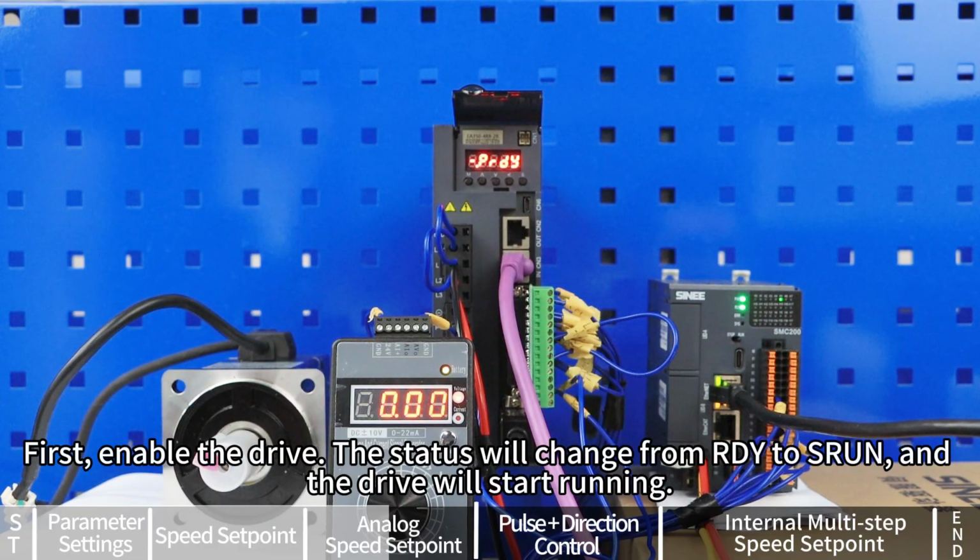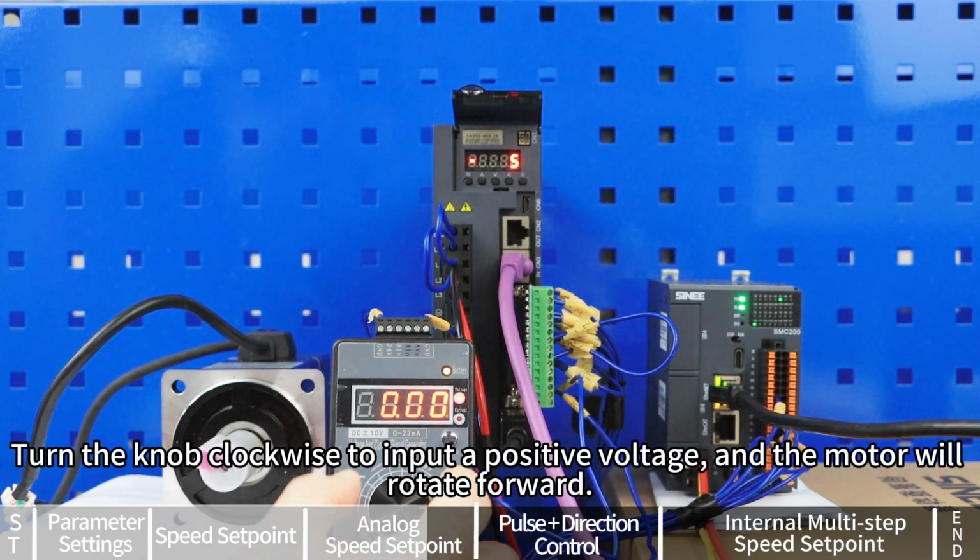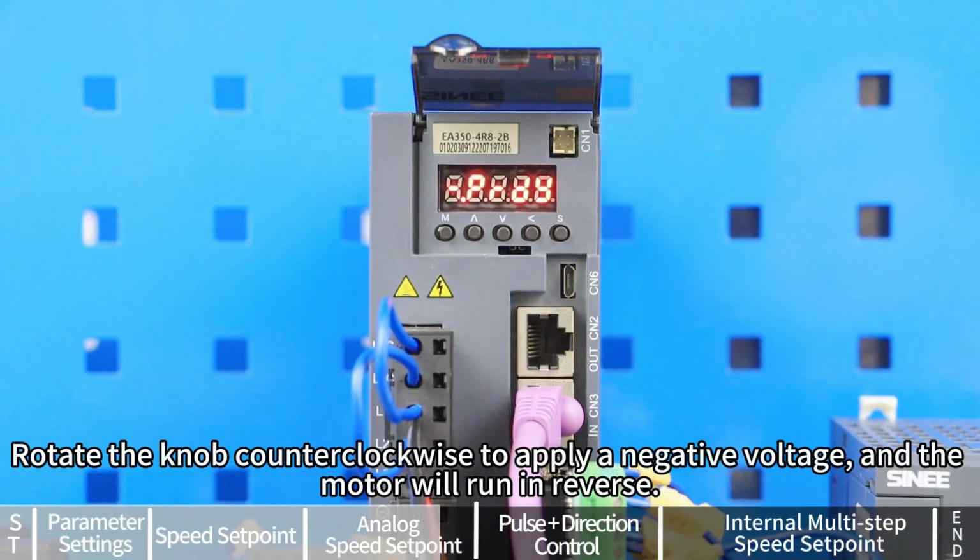First, enable the drive. The status will change from RDY to run, and the drive will start running. Use a signal generator to provide an analog input signal to the drive. Adjust the input level by turning the knob. Turn the knob clockwise to input a positive voltage, and the motor will rotate forward. Rotate the knob counterclockwise to apply a negative voltage, and the motor will run in reverse.